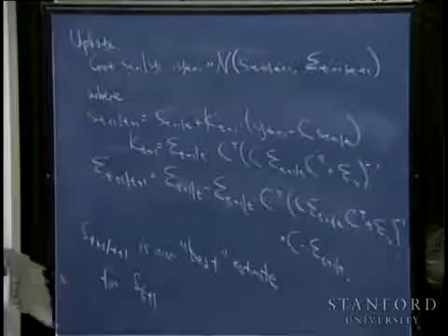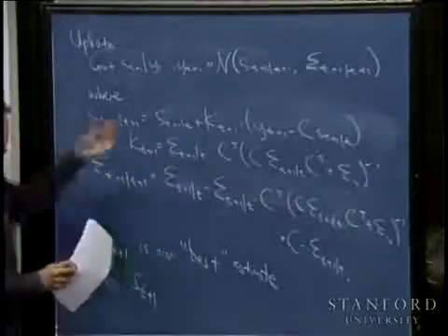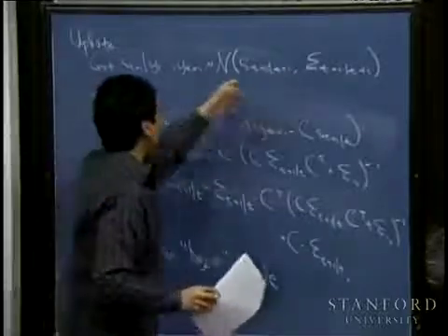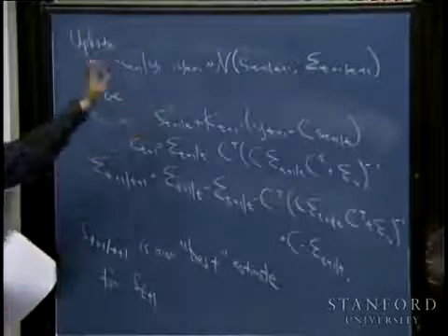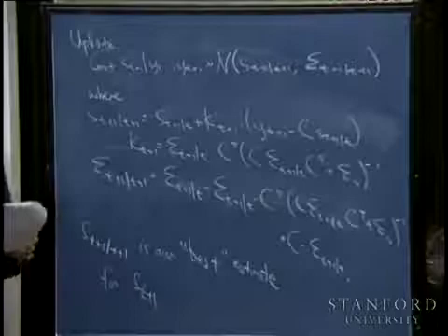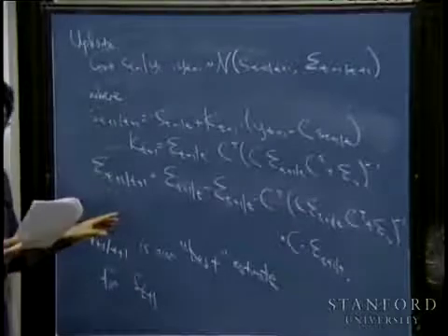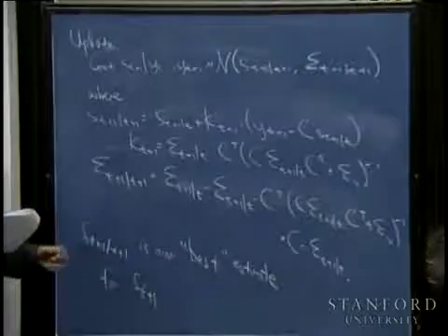Okay? And again, the correctness of these equations, the fact that I'm actually computing this mean and covariance of this conditional Gaussian distribution, I'll leave you to prove that at home if you want. I'm actually going to put this together with LQR control in a second, but before I do that, let me check if there are questions about this.